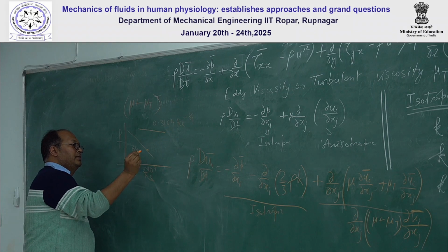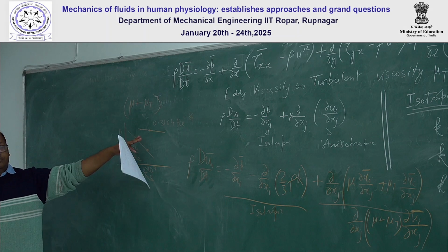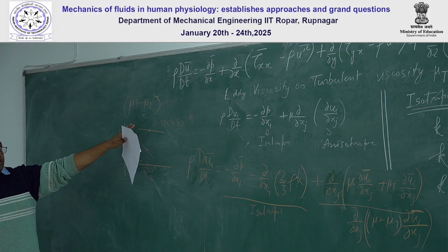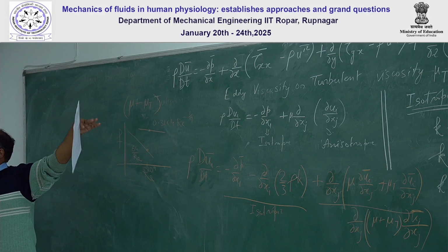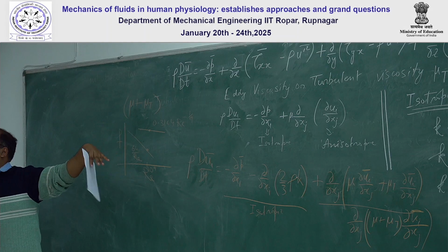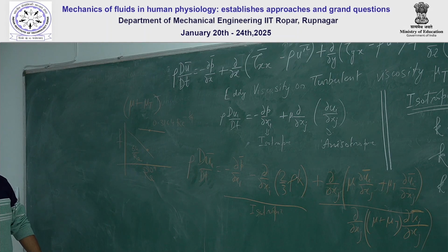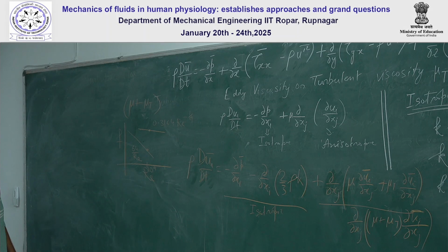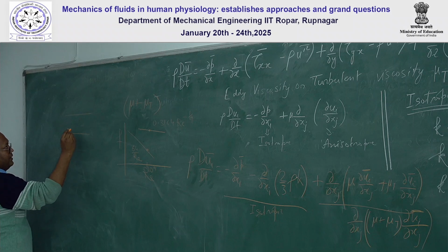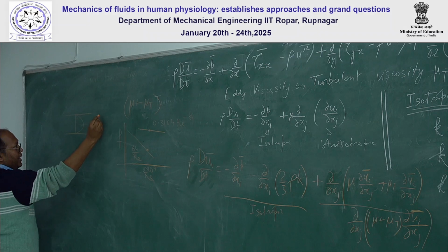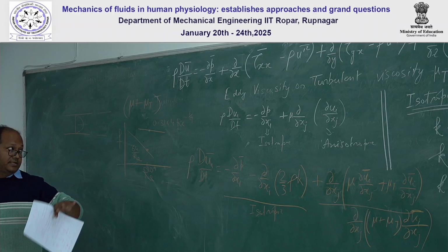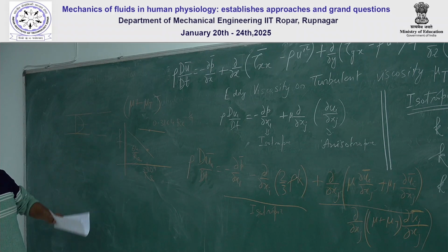So for the same Reynolds number, you know that for turbulent conditions the friction factor is much higher. So as if this mu_t is adding up to the fluid viscosity and is responsible for the increase in viscosity and the eventual increase in the friction factor. Physically, we know it is a parabolic profile here, and in comparison, due to lots of eddies there is intermixing going on, transverse mixing in the perpendicular direction.